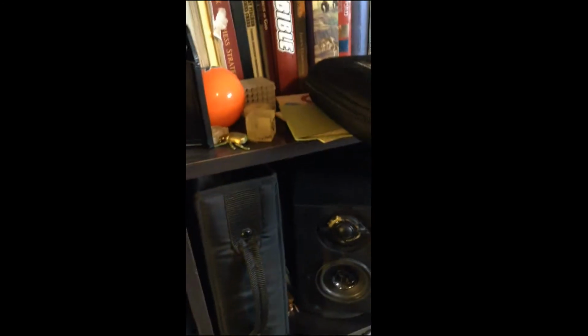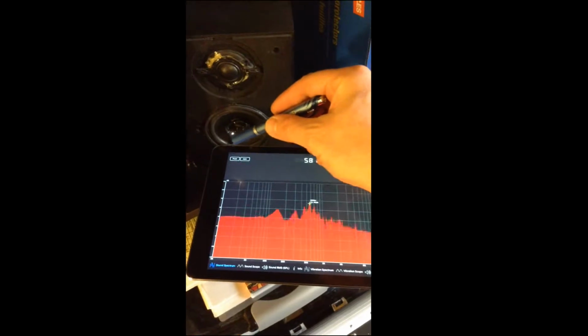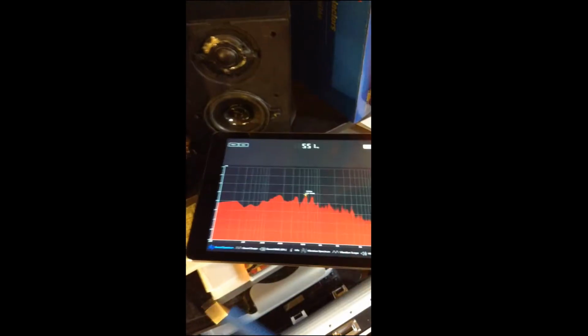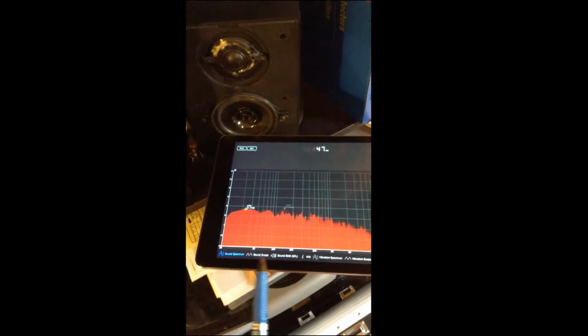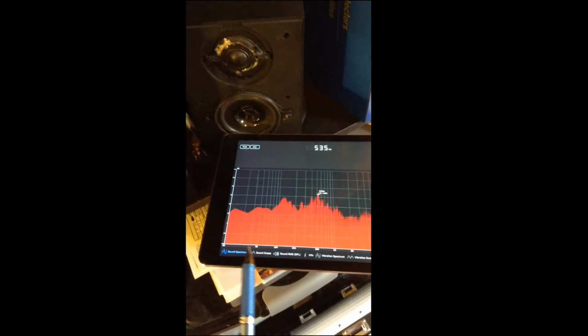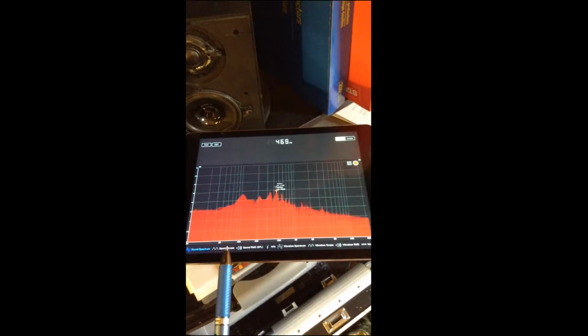We have a few limitations here. One limitation is the physical size of the microphone in my iPad, which is not very big. Sorry, I'm trying to adjust the screen here and it's not adjusting. There we go. Sorry about that. So the physical size of the microphone, which is very small, and this pinpoint hole opening, which you just saw, present a limitation to this low audio frequency spectrum. So our resolution at this low frequency range is not going to be very good at all.